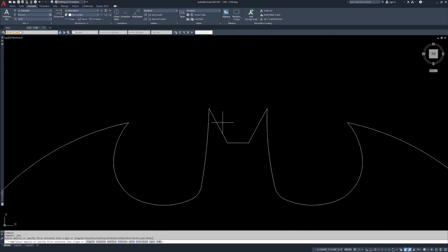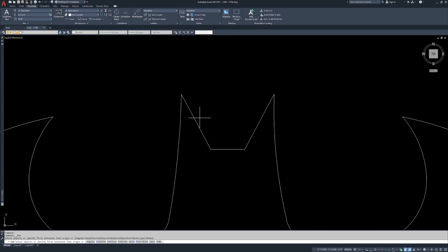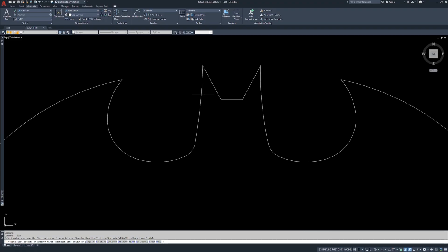Now you're going to notice, I'm going to zoom in, mouse wheel forward. When I get the mouse over an object, it's going to give me a preview of the dimension. This is 2 separate line segments here in this polyline, so it's going to break it up twice. Now, oftentimes you can get away with doing this by just mousing over it. And you say, you know what? Radius 3/4 of an inch, that's fine. I'm going to click and I'm going to drag it away.